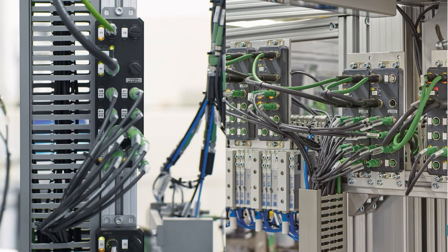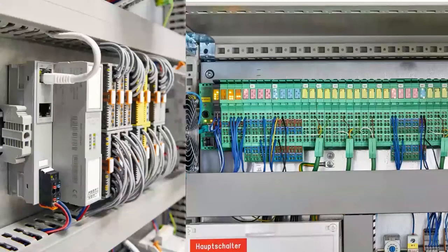This is big automotive. This is big conveyor systems, things like that, where you have a small amount of I/O spread out over real long distances. It's a much more cost-effective solution than to do all the junction boxes. And then, of course, you have the I/O in the cabinet. This is still the more popular variation, but in the cabinet, you have the idea of creating I/O stations and creating some modularity between them.